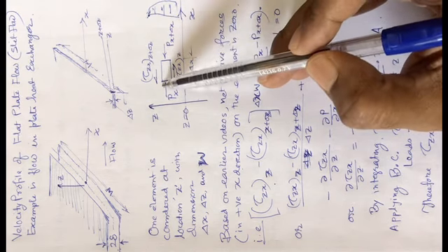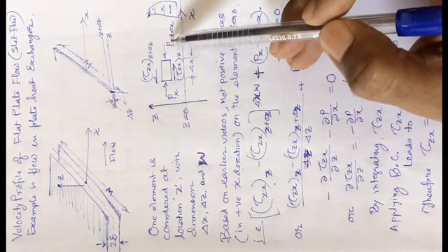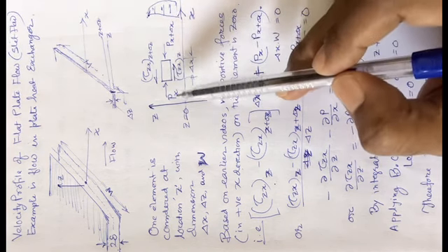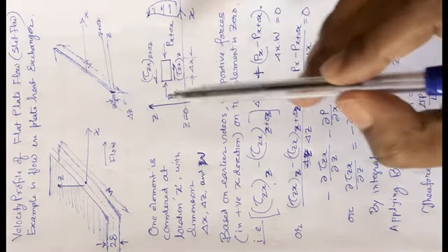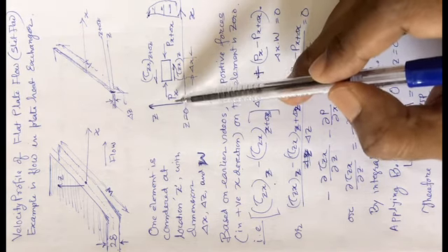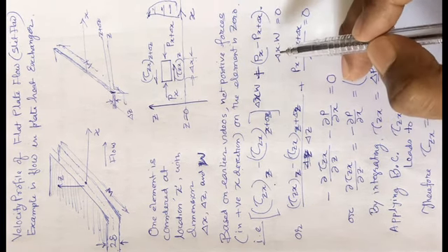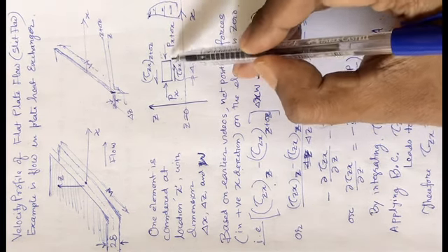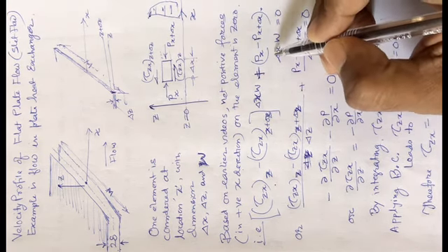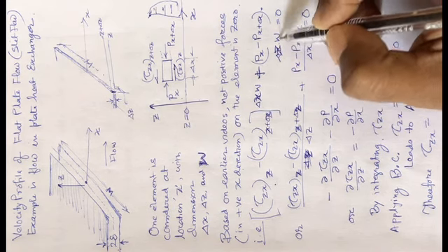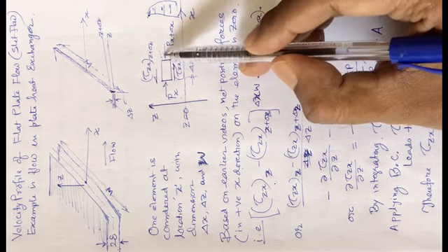Now what is causing the fluid to flow is actually pressure. From the left hand side there is P at x, and from the right hand side P at position x plus delta x. So now P at x is supposed to be greater, then only will the fluid be moving from left to right. So at P x, we are talking about positive forces, so P at x minus P at x plus delta x, the whole thing should be multiplied by this particular distance, that is delta z into W. So this pressure force is acting on this particular height and depth of W across this plane.